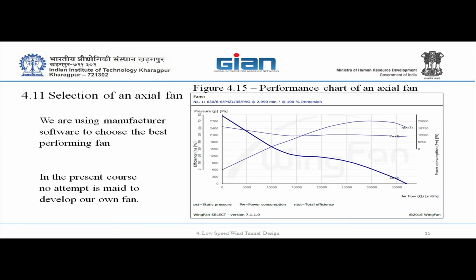This is the first thing I was checking when we got the fan. I told the guys, come and measure the velocity on the surface of the fan and see that they supplied what they promised. Surprisingly, I found, first of all, that the RPM is higher than what they committed for.